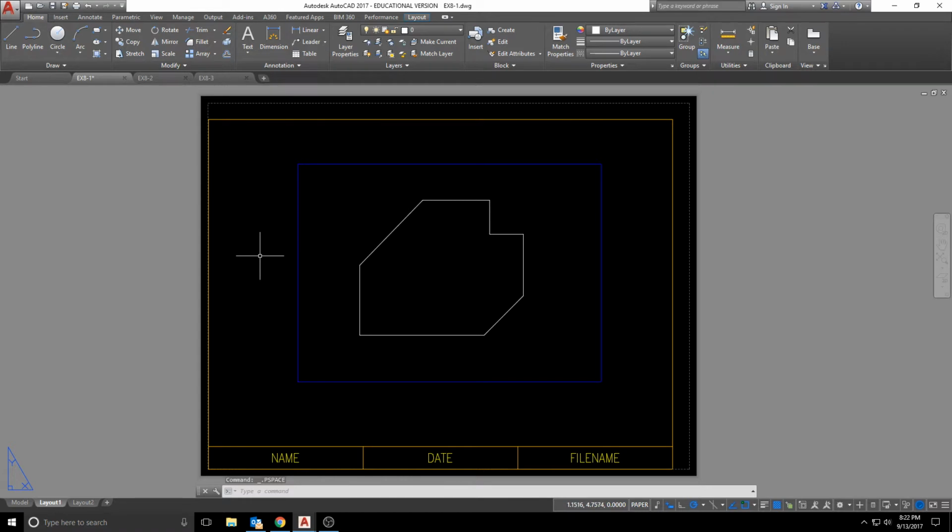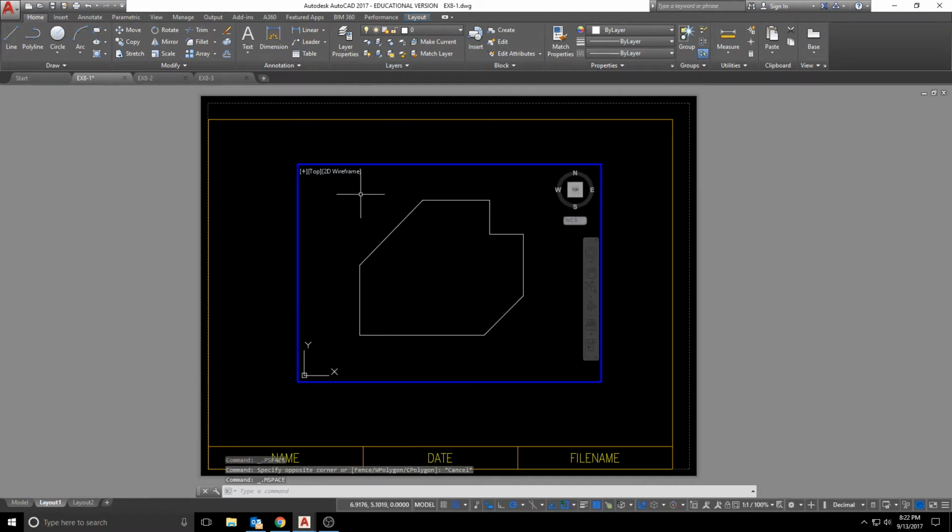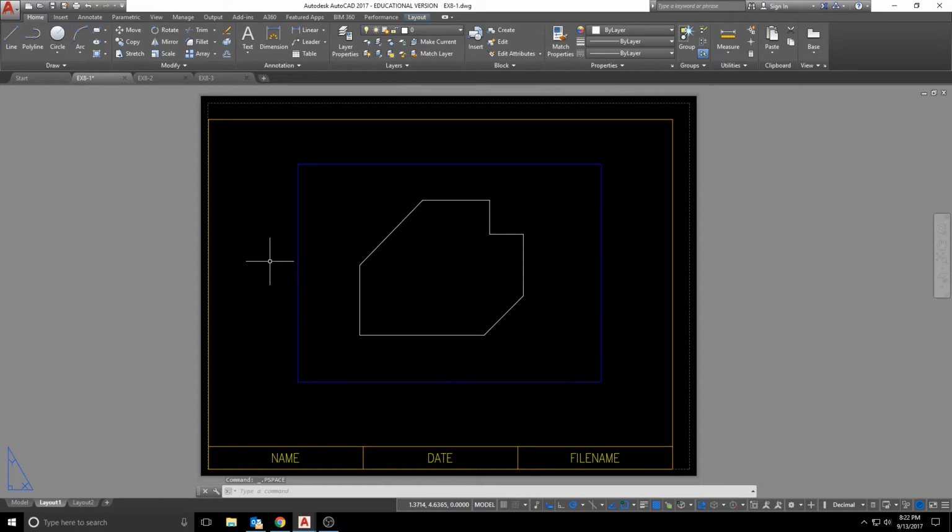The one thing that you want to make sure is that you're always working in paper space when you're placing your dimensions. There's two ways to tell. If I double click inside this viewport, you can see that I get my view cube up here, my navigation buttons on the side, I've got a UCS down here, and it's got all the view modes and stuff up here at the top of the screen. It doesn't really tell me anywhere else that it's in model space, but if we just look for all of these indicators, then it's a pretty good idea of what we've got going on. When I double click back outside of it, all of that stuff disappears, so that lets me know that I'm working in the layout tab.